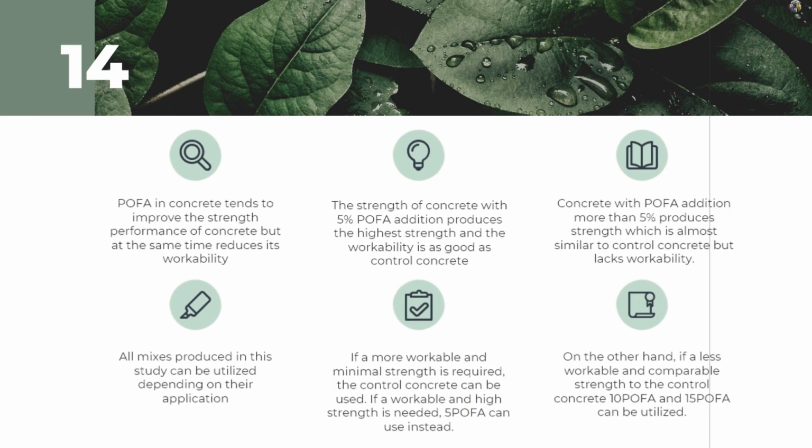Next, this slideshow summarizes all my main ideas in this study. POFA in concrete tends to improve the strength performance of concrete, but at the same time reduces its workability. The strength of concrete with 5% POFA addition produces the highest strength, and the workability is as good as control concrete. Concrete with POFA addition more than 5% produces strength which is almost similar to control concrete, but lacks workability.